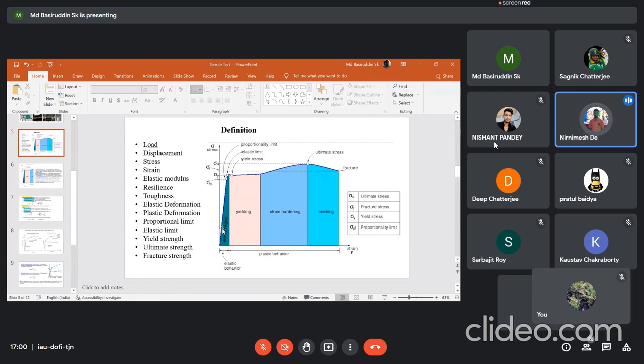Elastic modulus is basically the resistance of a substance to being deformed elastically when a stress is applied. And what is actually responsible? Obviously we need to go to the atomic scale, where the binding force between two atoms is responsible for the elastic modulus. In simple language, the modulus of elasticity is a measure of the stiffness of a material, meaning materials with a higher elastic modulus are much stiffer than metals with a low elastic modulus.